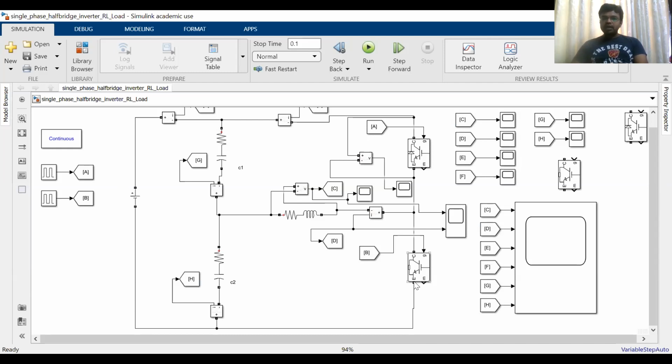Here, because you are not using any feedback diodes, you will get the high voltage spike. The high voltage spikes are coming because you are not able to provide the discharge path for the inductor energy. The switch cannot allow the current in the reverse direction, so the current will go to zero immediately, and because the inductor is not allowing the current to be zero, a high voltage spike will be obtained.